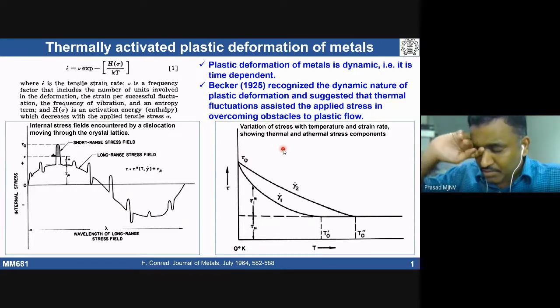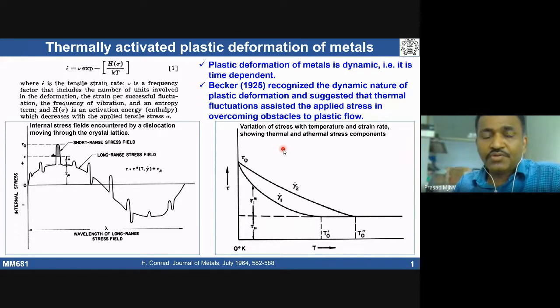Okay, so let me start today's lecture. In my previous lecture, we had discussion about fatigue, cyclic plastic deformation, where we talked about crack initiation, crack growth, and what kind of microstructure evolution takes place during cyclic deformation. We also had a little bit of discussion about fracture mechanics, a mode of understanding the fatigue behavior of materials, where we talked about Paris law, and how the crack growth changes with the stress intensity factor range.